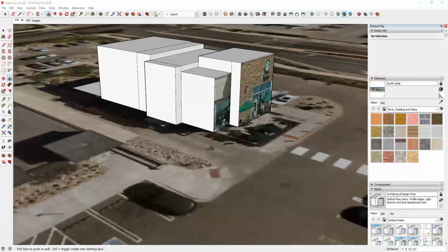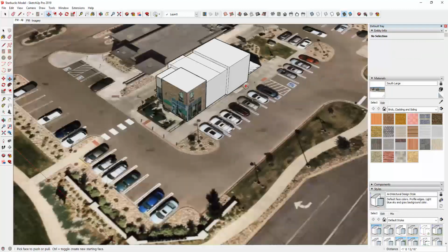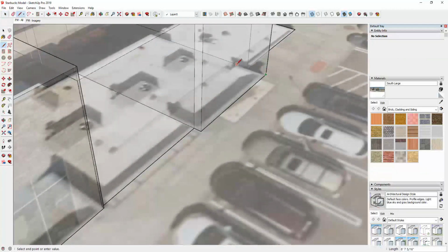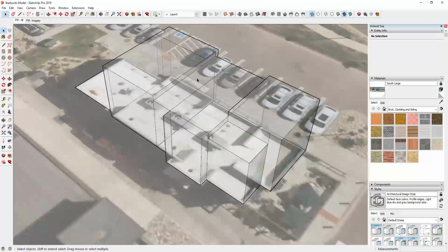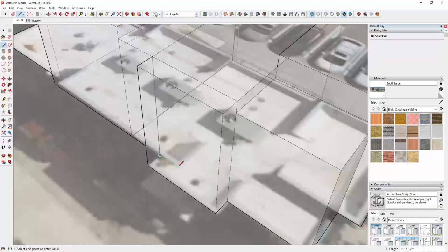And I'm just making these fine adjustments until the building looks the way that I want it to look. So you can see how I'm drawing lines across these edges, and I'm just push-pulling things up and down in order to match the way that this building looks with the actual photos that I've taken. So for example, what I'm doing right here is this building has a parapet that you can see from the NEARMAP image that I brought in.